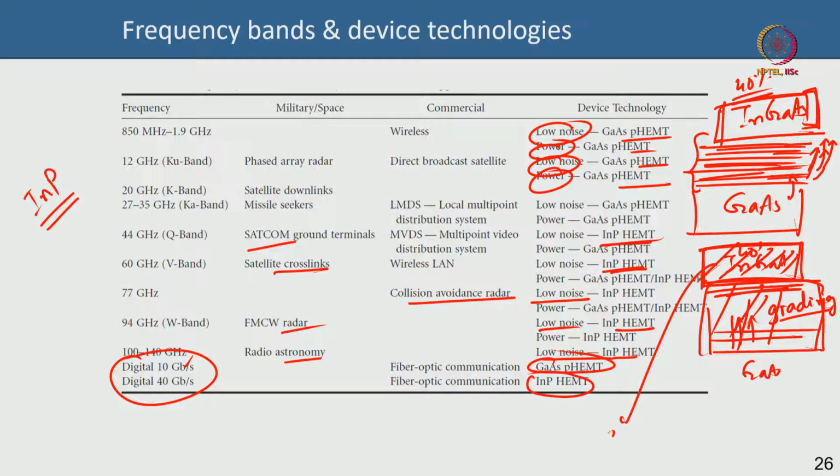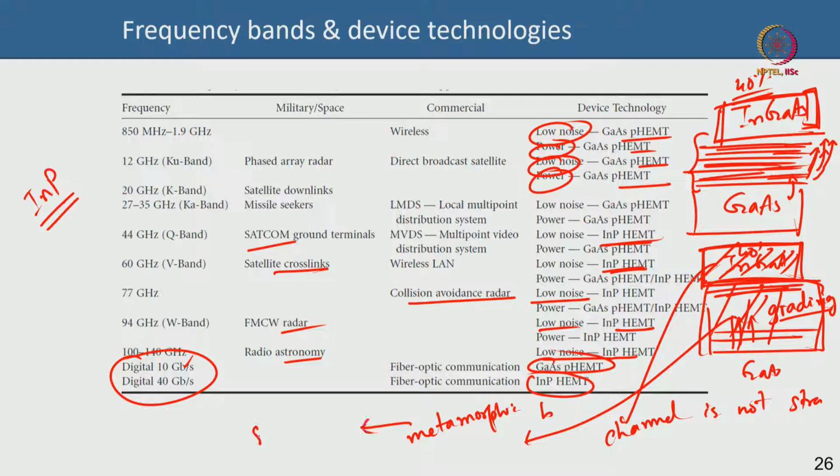So, then this channel is not strained. This is called metamorphic buffer. This transition that you are growing is called metamorphic buffer, because you are essentially allowing the strain to relax. This metamorphic buffer is strain relaxed. You are relaxing the strain, but you are also managing the dislocations. Because you are relaxing the strain gradually, your dislocations will generate, but you do this strain engineering or dislocation engineering in such a way that you do not allow these defects and dislocations to propagate to the top InGaAs channel.